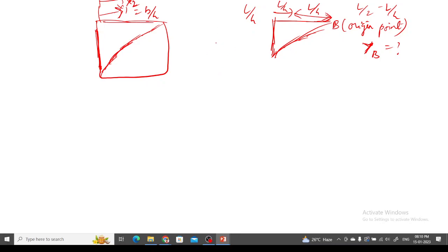See, that depends on where you are actually taking the... Can you repeat the question again? If my reference point is at the left hand side, then whatever... See, reference point means the point where slope or deflection is 0. So maybe here we are having the reference point. In this case, we are considering area and its moment from the left hand side diagram. And if I choose the reference point at the right hand side, then I will take area and moment from the right hand side.